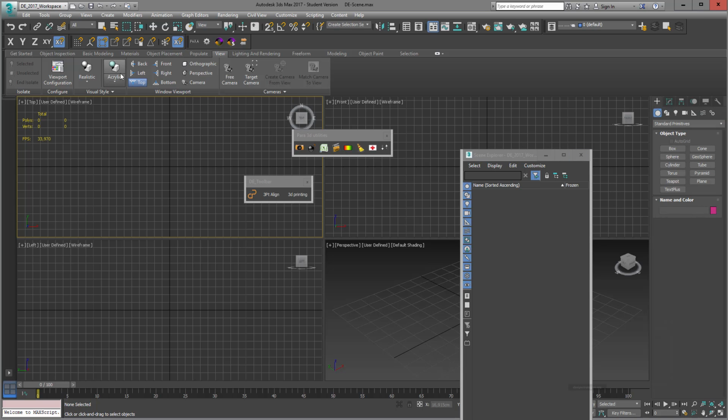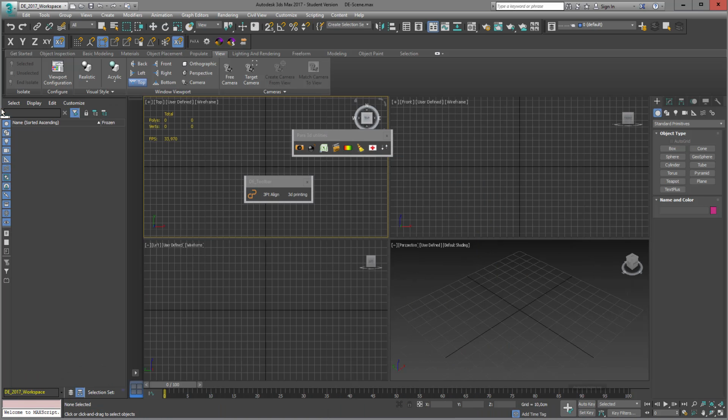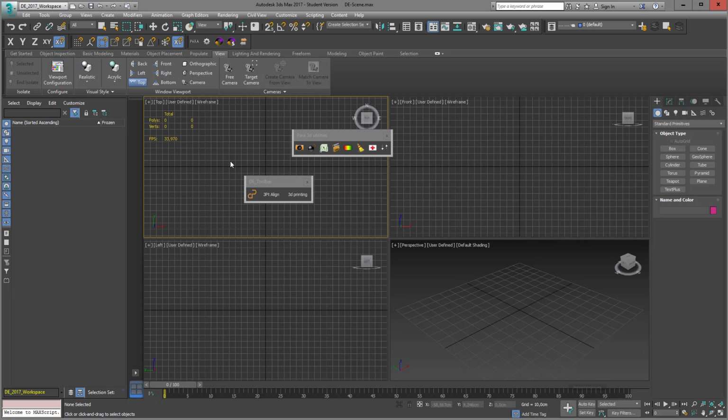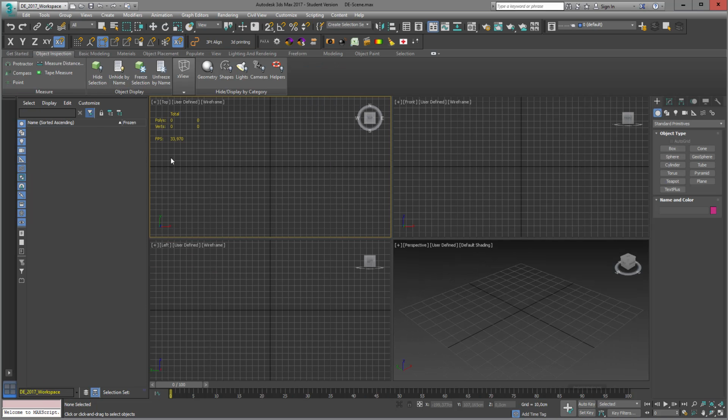If you don't want to use a DE workspace, then this is not a big issue. You can just use the design standard workspace. It's also quite common to switch between these workspaces while using, especially with this default with enhanced menu. And if there are any issues, you just go to reset to default state. So sometimes if there are some things with your toolbars, just use this button and you get a refresh of your workspace.